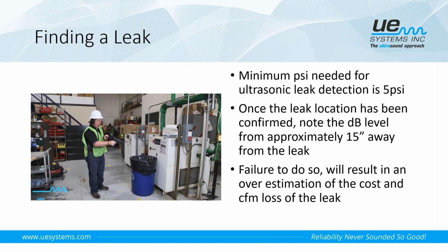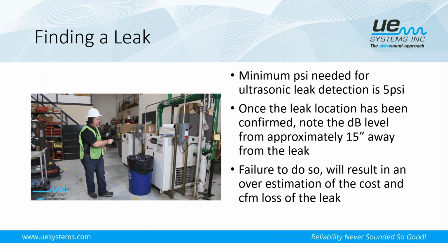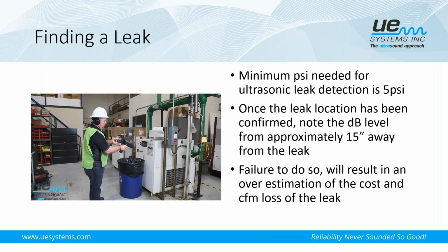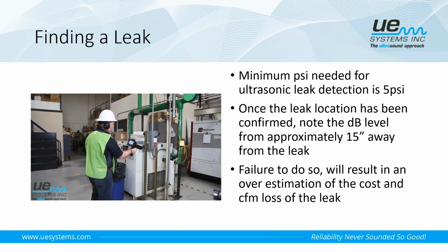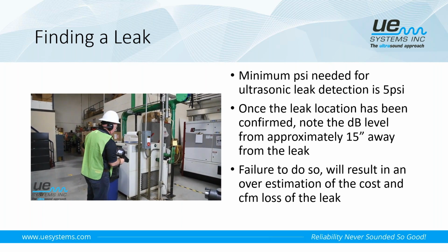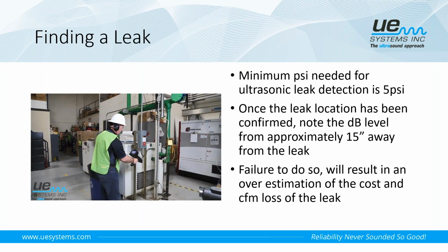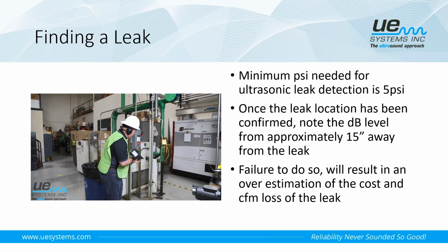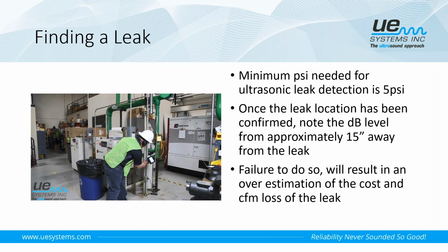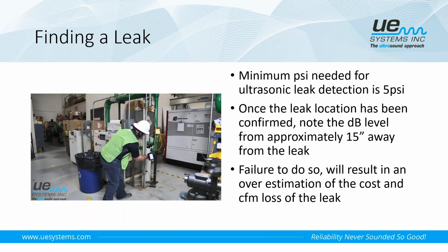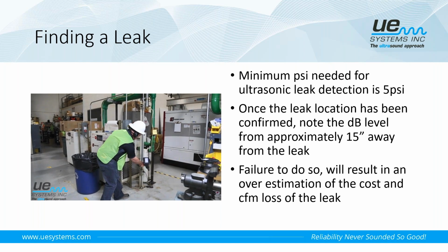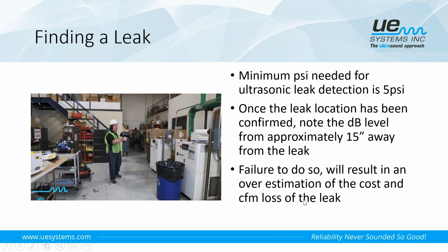Now the scanning module that's on that UltraProbe 15,000, again, it's rated for distances up to 50 feet away, and that's at the maximum sensitivity. So we can potentially hear the sound up to 50 feet away. But you can see as we're moving closer to where that leak is coming from, now we're ready to pinpoint using the rubber focusing probe, and there's the leak. And then if we were going to take that reading, we would just simply back away approximately 15 inches and note the decibel level from that distance.